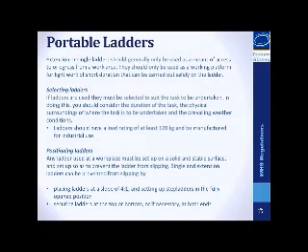The positioning of ladders. Any ladder used at a workplace must be set up on a solid and stable surface, and set up so as to prevent the ladder from slipping. Single and extension ladders can be prevented from slipping by placing the ladders at a slope of 1 to 4 and setting up step ladders in the fully opened position, and securing ladders at the top or bottom, or if necessary, at both ends.